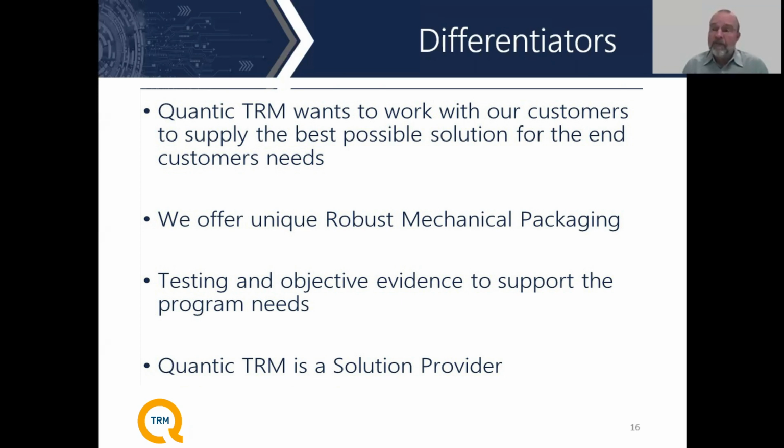So really the big thing here is we like to work with our customers, find out really what it is you're doing. Even with something like a Wilkinson Power Divider, there are trade-offs to be made. Is output VSWR your most important parameter? Is input VSWR your most important parameter? Is amplitude or phase balance, or in some cases, isolation a driving parameter? We need to know those things. So we like to have those discussions with our customer to find out really what it is they're trying to accomplish, and therefore we can design a part that meets those needs.